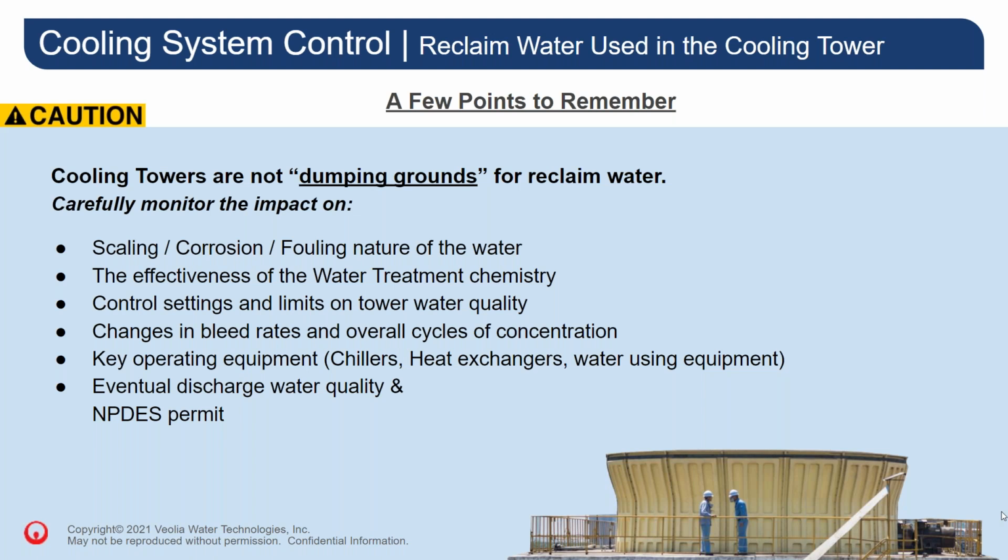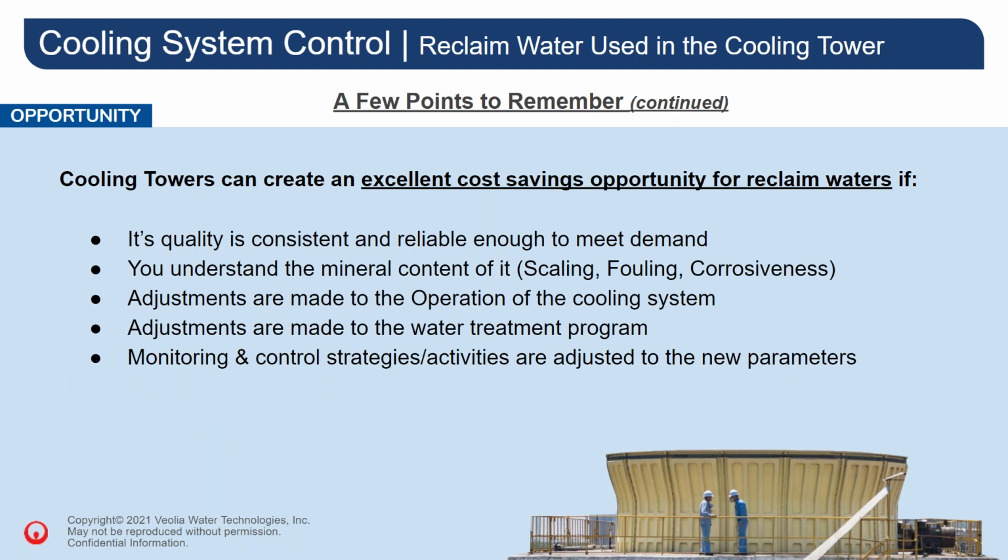In these situations, it's more critical than ever that you monitor and control water quality even more stringently and also have in place a process equipment monitoring program, as Phil talked about earlier, and make sure that the key system components in your cooling loop are being adequately protected and continue to operate both reliably and efficiently. So I don't mean to scare anybody away from using reclaimed water as a cheap source of makeup. You won't find a bigger proponent of reclaiming and recycling water than yours truly. Properly planned for and managed, this is a real opportunity for cost savings and overall sustainability and water footprint reductions by implementing this type of initiative.